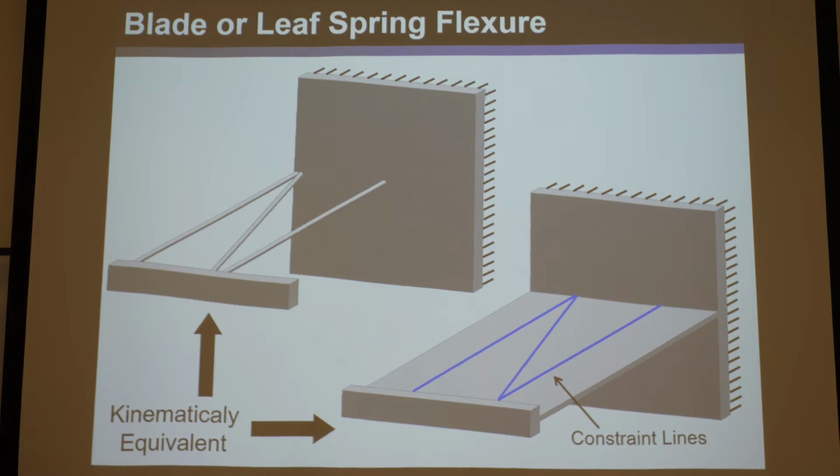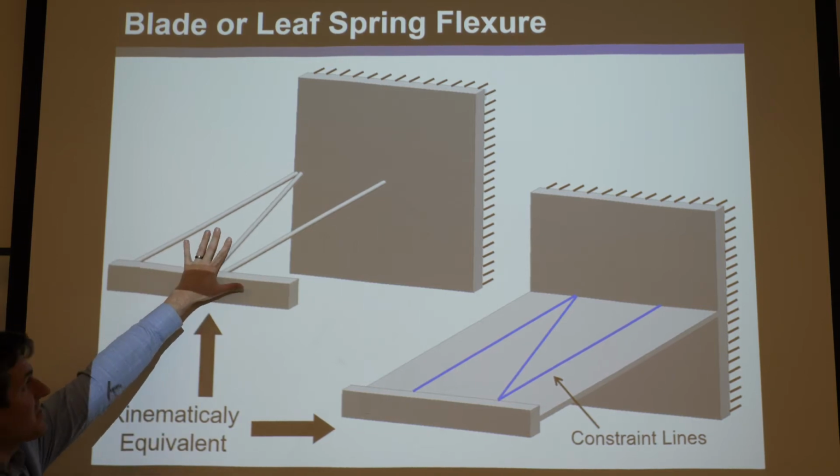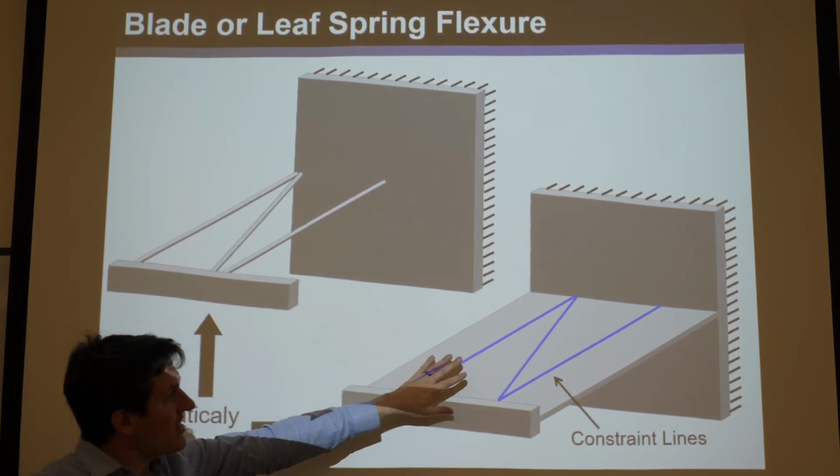So the truth is, over and exact constraint, even though in theory it's like black and white, where you're either exactly constrained or over-constrained, in reality, when you add all the gray, and your ideal constraints aren't infinitely stiff and infinitely compliant in different directions, with all these assumptions, you actually allow reality to add its grayness to it. You're actually never perfectly exactly constrained. You're just closer to exactly constrained than over-constrained. And in this case, this scenario would be closer to exact constraint than this.